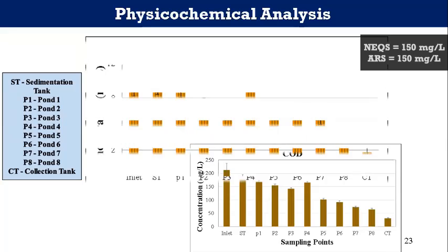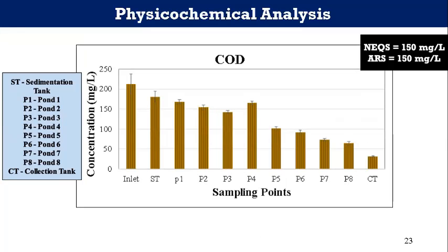COD, the chemical oxygen demand, is an important parameter for measuring organic pollution in water and is used in some states as a national standard to examine aqueous organic pollution. Wetland detention, decomposing microorganisms, and temperature in a water body contribute to low COD concentration. Observed at the outlet, this may be attributed to biodegradation of the organic matter by microbial bacteria in the wetland, and trapping of particulate organic matter by wetland plants.